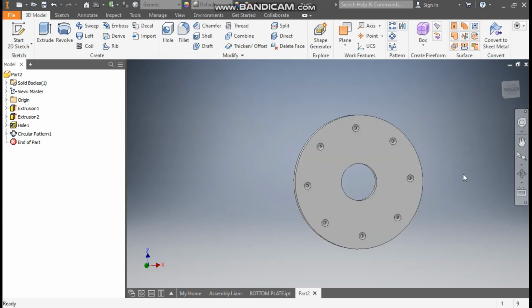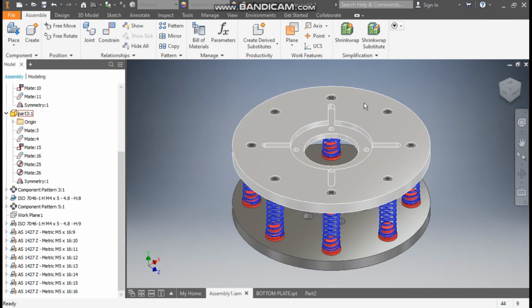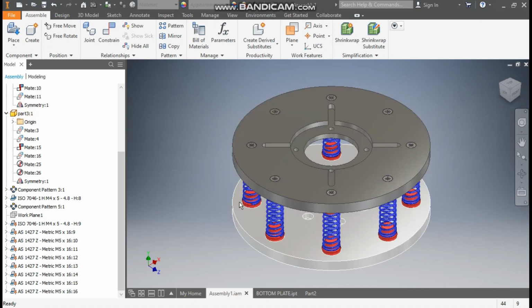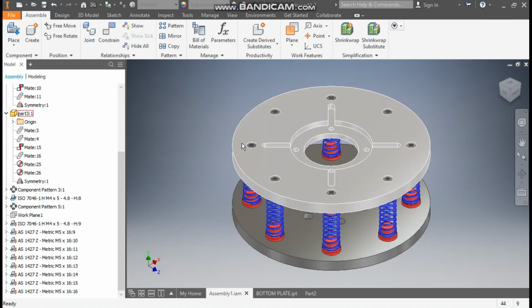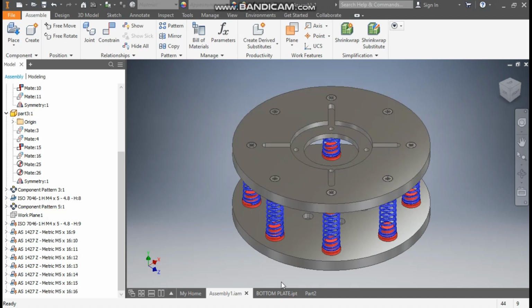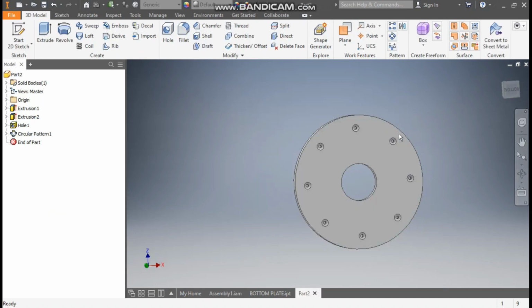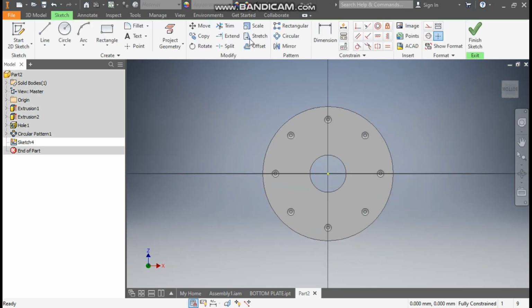Okay, till here the profile was almost similar to the previously made. So now the next thing which we have to do is the cut profile. Go to assembly. Here you can see a cut profile. This profile will be at the side of the countersink profile. Okay, the countersink face. Select this face, go to create sketch, take the circle command from the center point, make